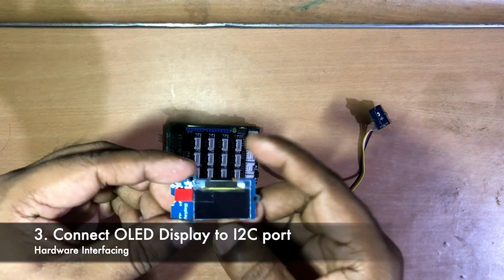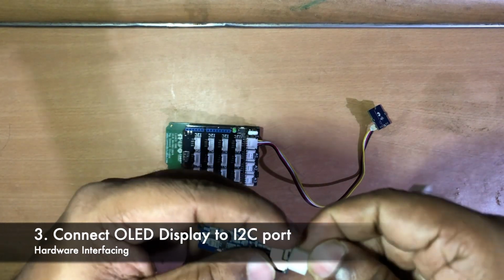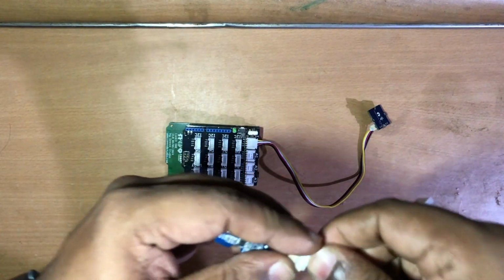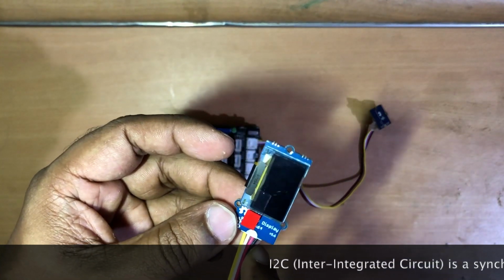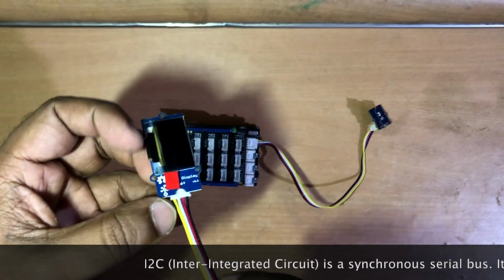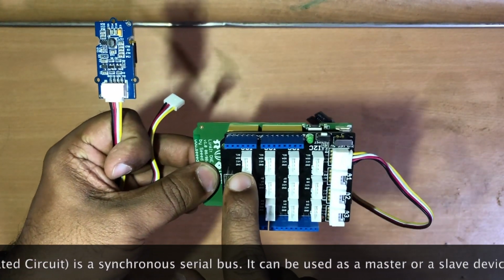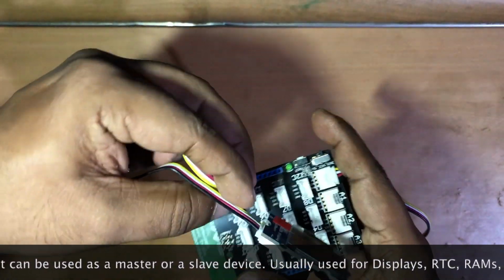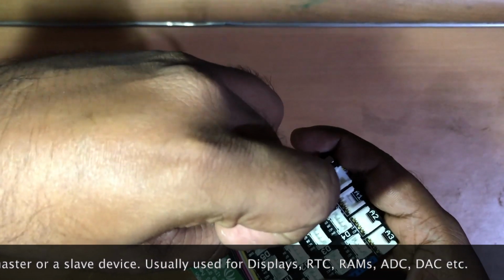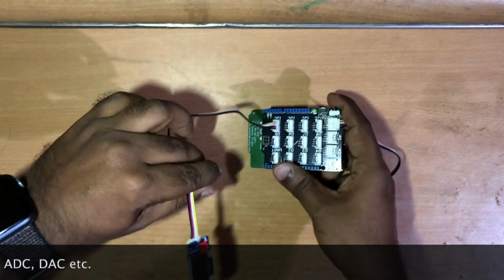Now let's take the OLED display, and at the back side of it there is a connector. So let's connect the Grove cable, and as we know, the OLED display is an I2C interface display. So we'll have to connect this to the I2C connector on the Grove. You can connect it to any of the I2C connectors. I'm going to use the first one. Okay, so I've connected the display.